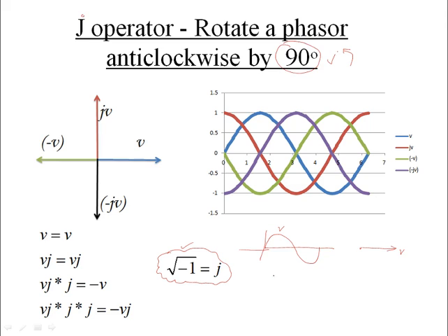That is my phasor. And if I multiply V by J, it is actually leading by an angle of 90 degrees. This is my 90 degrees. This is my VJ. Now how does it look in the waveform? It will be leading. This is 0 degrees now. This is again the 90 degree leading case. So this is the waveform which I am going to obtain, the leading condition.